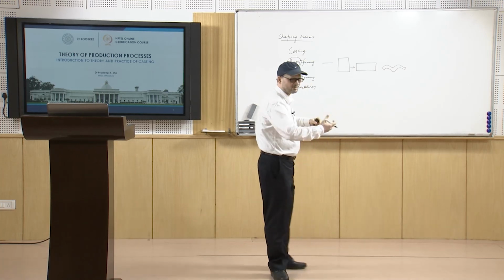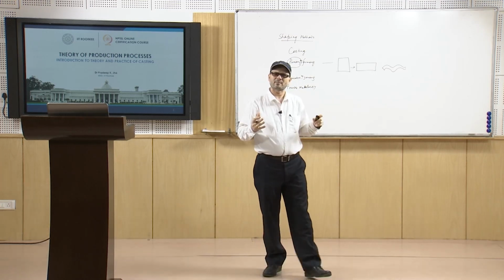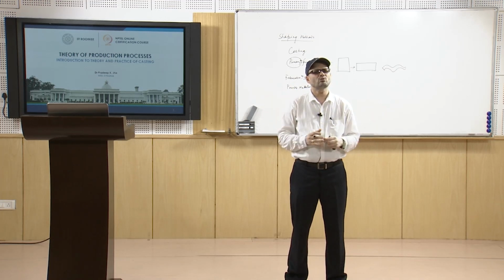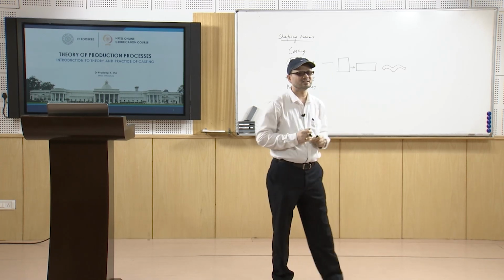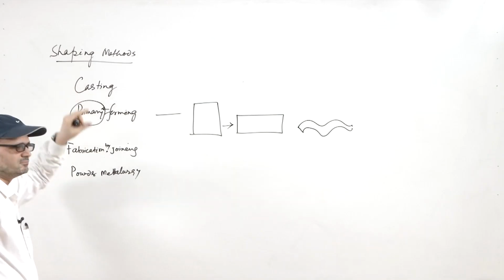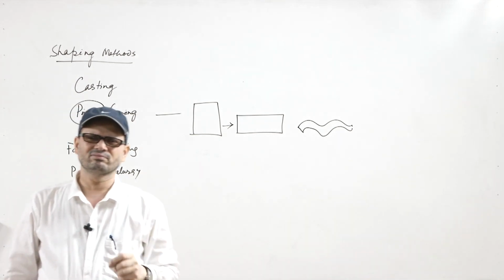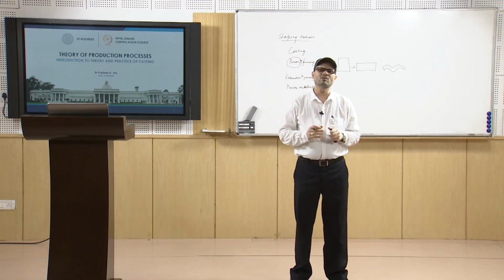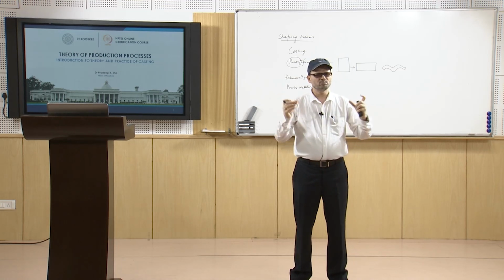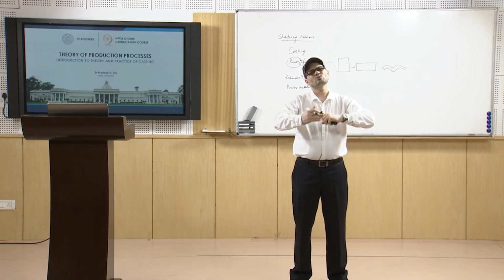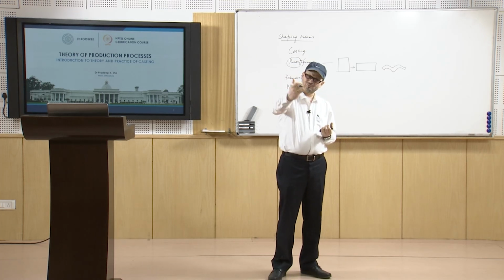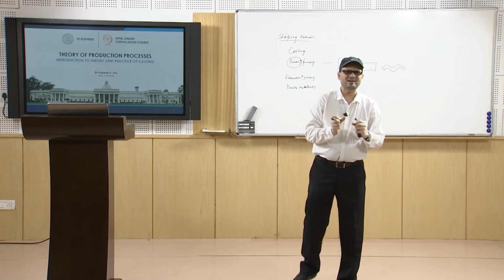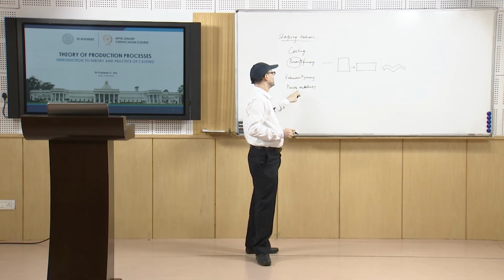When you melt, the ceramics will behave differently and the casting itself will be difficult, because once you cast you cannot ensure the homogeneity of the ceramic particles throughout the mold. These are the challenges to be faced. They are taken care of by adopting the process of powder metallurgy, where you have powders of different materials, you mix and blend them properly, then go for heating. You do not go to the melting stage, but come to the sintering stage, use pressure and compact it, so that a bond develops between the particles. This way you get powder metallurgy products.